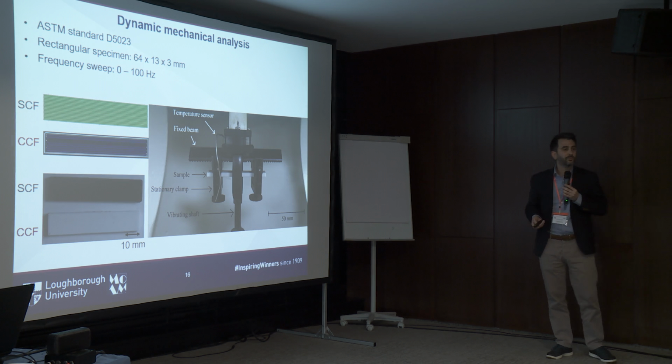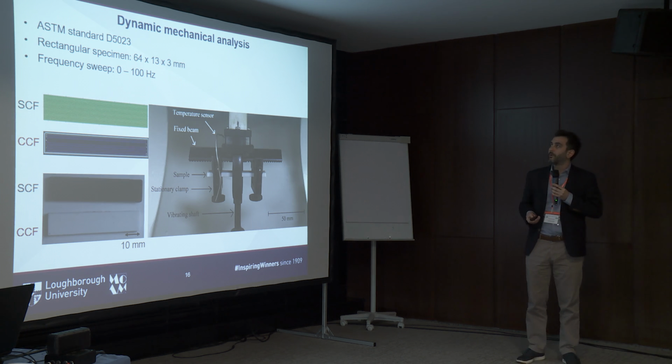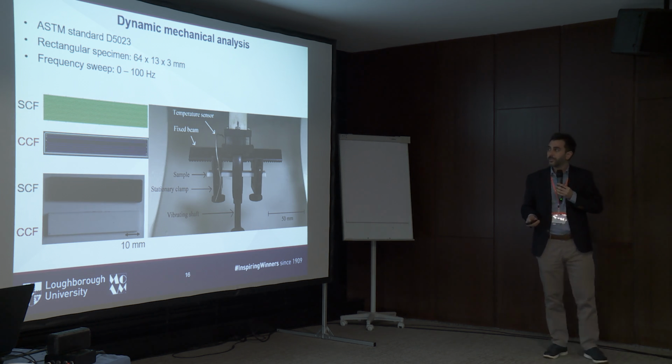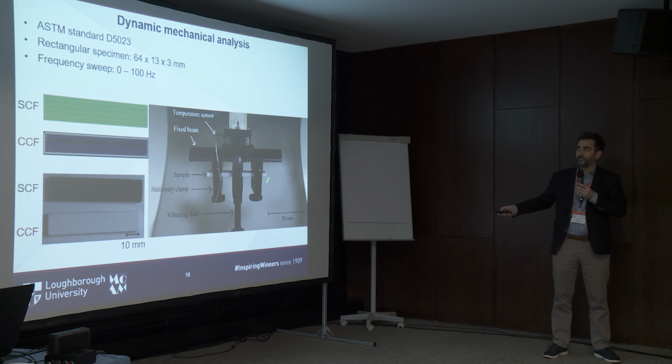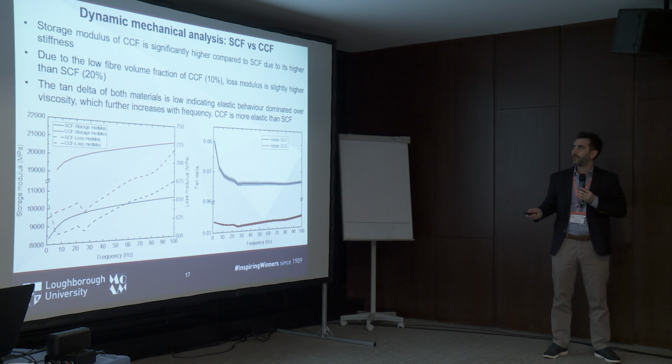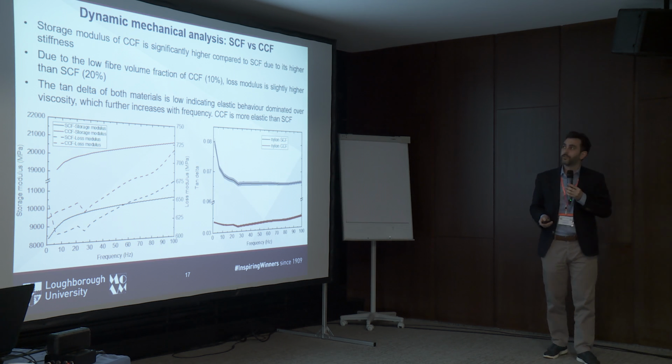Okay, let me now move to some dynamic results. We also perform dynamic mechanical analysis. This is the setup of the DMA. This is the specimen we have used, 64 by 13 by 3 millimeters of thickness. And we have performed a frequency sweep from 0 to 100 hertz. These are our results from these investigations.